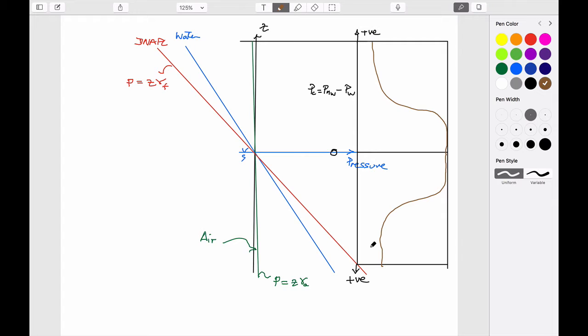And so the only relevant ones to look at are above the water table, which by definition would be the vadose zone, which we're talking about today. So in other words, a fancy name for unsaturated. Of course, it's not unsaturated, it's actually partially saturated, so it's a misnomer, but nonetheless. And this is the groundwater zone.